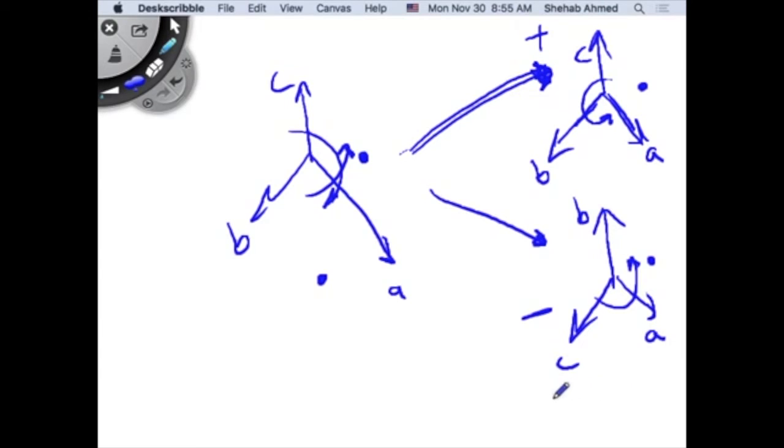And then there's another one: you take this and chop it up into what's called positive sequence, negative sequence, and zero sequence. Zero sequence is, these will be the three-phase voltages, but they will all be in phase, right? I don't want to talk about that too much now, but actually we can, because when you are supplying a motor, applying positive sequence balanced, what happens?